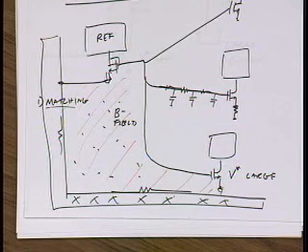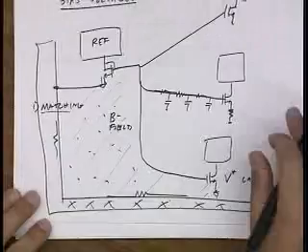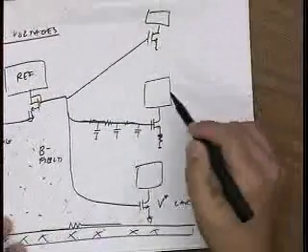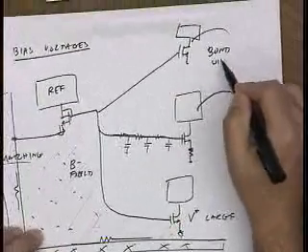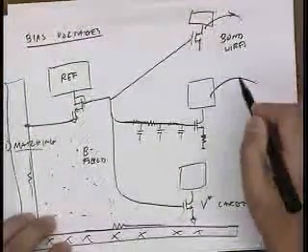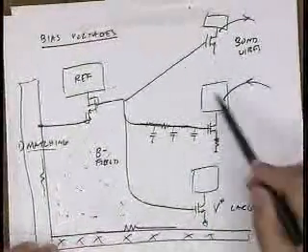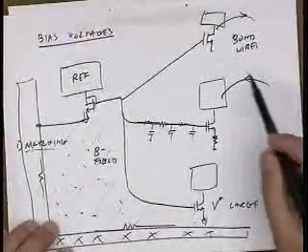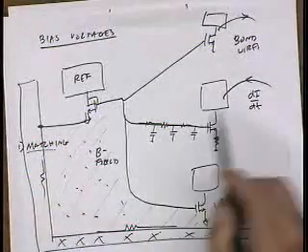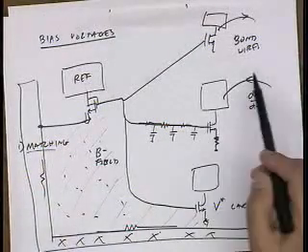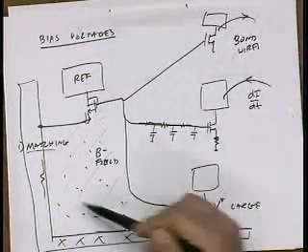So you have a change in current. Maxwell's law says you have a magnetic field. Yeah, it's all over the place. In particular, one big source of it are bond wires. So typically bond wires are going off chip. They carry large currents. And if they're carrying high frequency signals, there's a large dI/dt. And so this generates magnetic fields that can couple into your circuit.